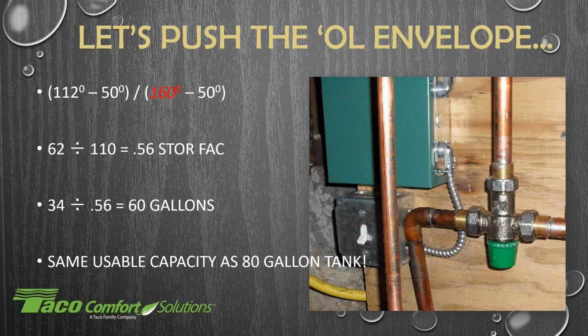Now, if I put an 80-gallon tank in my boiler room, it's a 6-foot closet. I have 8 zones of radiant in my house. So if I dropped an 80-gallon tank into my mechanical room, I have stuff on the wall on the back of my mechanical room that I'd never see again, meaning manifolds and actuators and controls. I'd have to remove the tank in order to access any of that area. So by keeping the smaller tank in my home and increasing the water temperature going out, it allowed me to not have to change any major equipment in my home in order to satisfy my heating demands. All right, any questions out there?